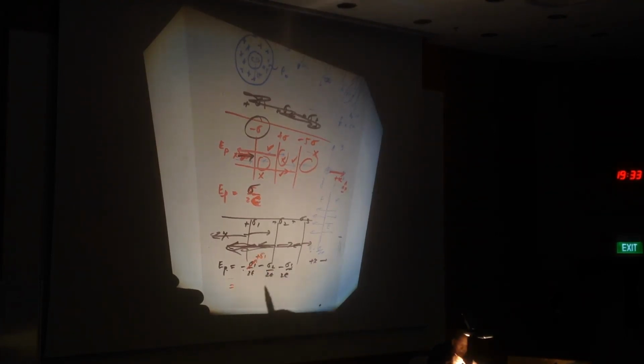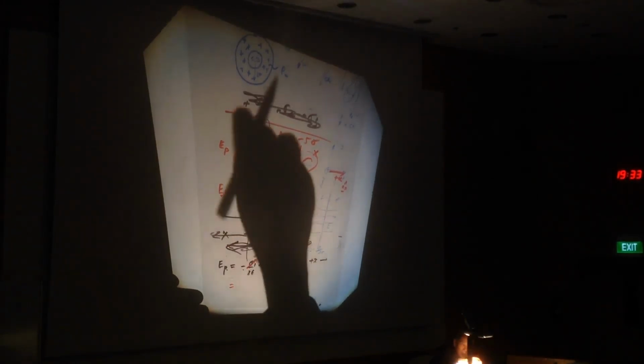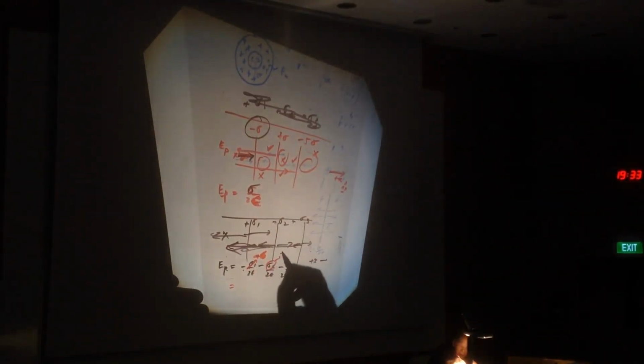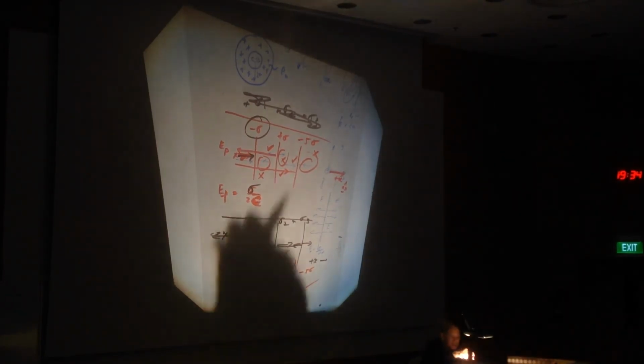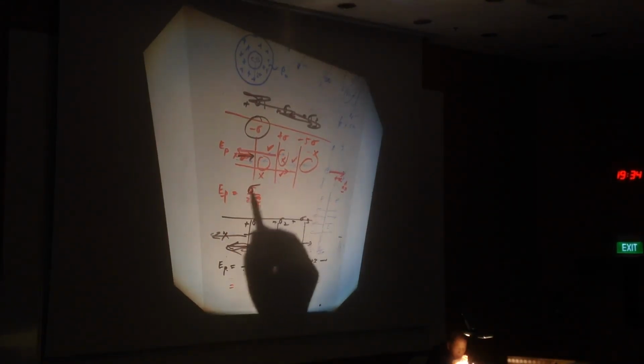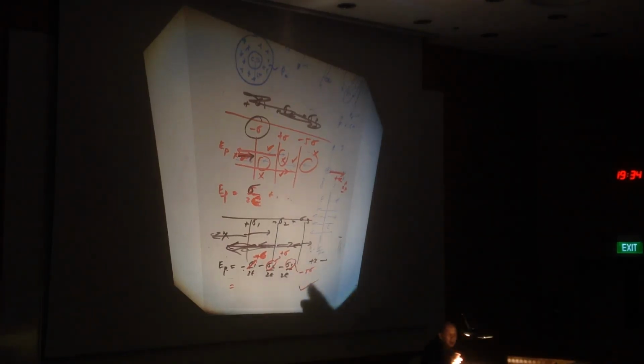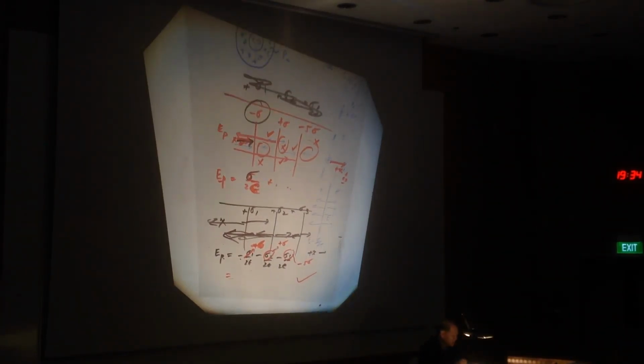Now I replace sigma 1 by plus sigma, no problem. Sigma 2 by minus sigma. What was given to me here? I replace sigma 2 by minus sigma, replace sigma 3 by plus sigma, and then simplify, that is the answer. It will coincide with this one if you continue doing it without the complication of double counting.